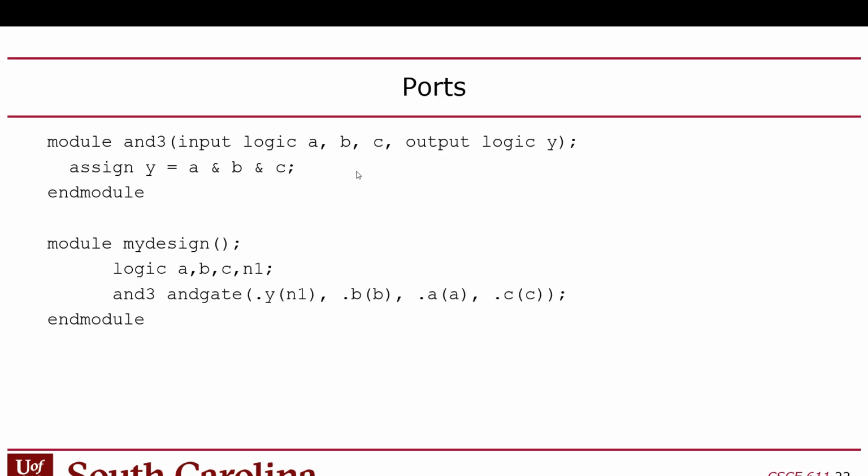Yes? Just to double check, you're saying that you can provide the arguments in a different order? Yes. You can put them in whatever order. Now, you might say, why complicate it? Well, the reason they use this syntax is because modules often have tons of inputs and outputs, right? This is a little misleading. It's very uncommon to see any module with only 4 ports. Usually they have a couple dozen ports. And so typically, like I said, you'll see them arranged on multiple lines. It's not like a function in a regular programming language that usually only has a handful of parameters. They're usually a lot.